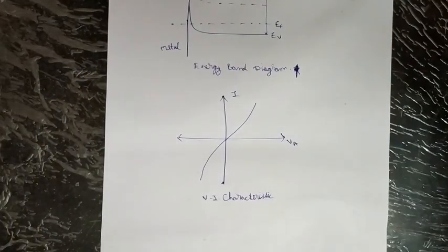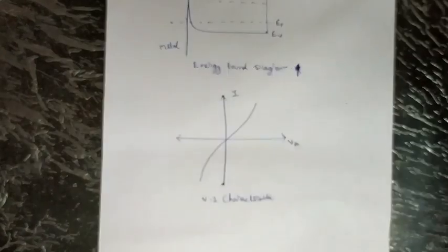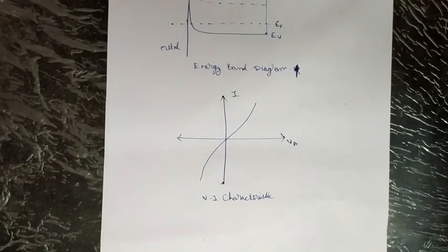Electrons diffuse from the N-type semiconductor and leave behind positive space charges. The depletion layer increases until the repulsion of the space charge stops further electron diffusion. The work function is measured from the Fermi level to the reference level, where an electron becomes a free particle.